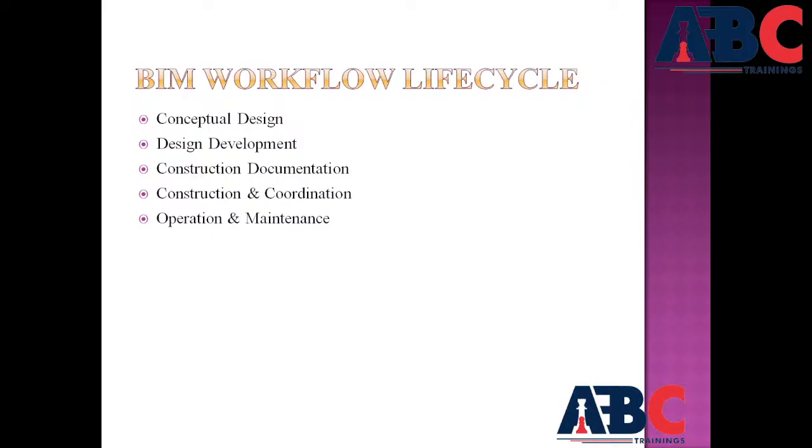Construction and coordination. During construction, the BIM model acts as a central coordination model for the contractors and the project managers. It helps to track the progress, identify conflicts, and visualize the sequencing. Key activities are model based scheduling and construction sequencing, clash detection using tools like Navisworks, on site coordination, quality checks, and cost management of the BIM model.